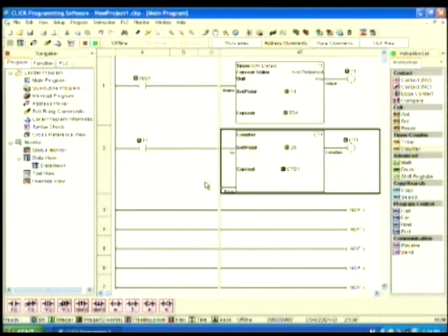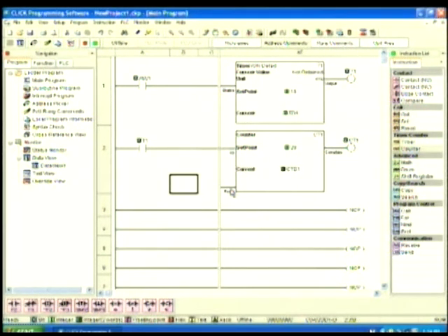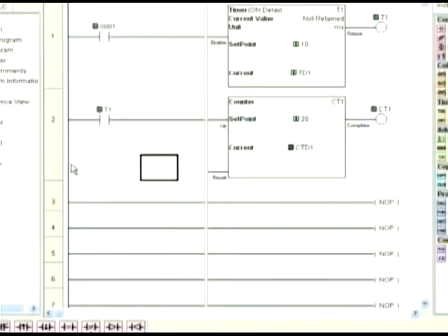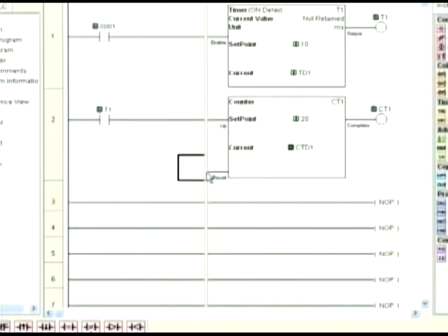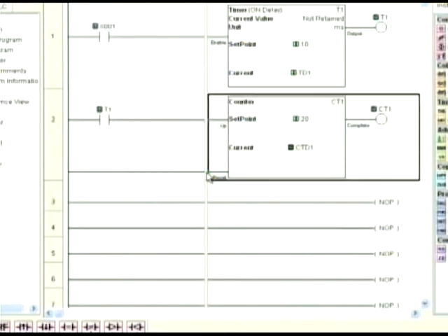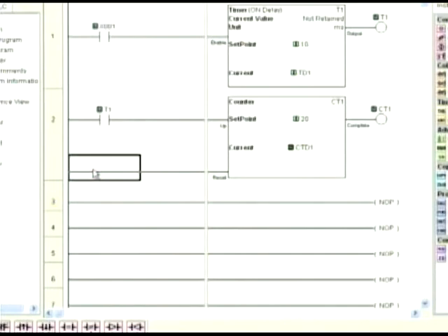And we notice something different on this one, Shane. If you look right here, we've got a reset leg that doesn't have a wire going over to the far side. Well, that causes an error. That's going to cause an error. So the easy way to do it is put your cursor right there, hold down the control key, and arrow over, and draw the wire in for it. Now everything's all happy, and it'll compile without giving you an error.